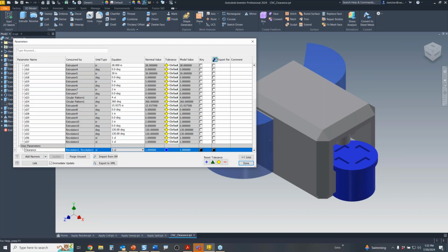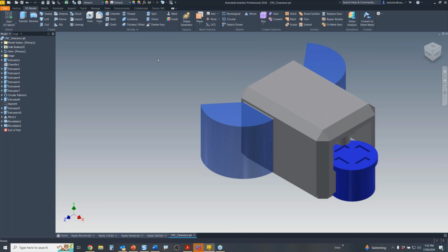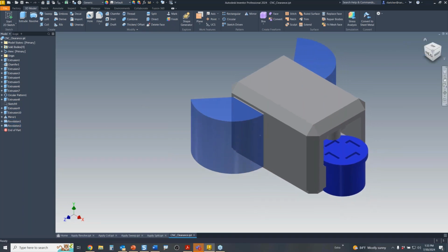And now I could do all kinds of things with this, because some of our parts have clearance zones. Sometimes you want to show them, sometimes you don't. So you can build in that. This is something you might do with a model state in the newer versions of Inventor. But before we had model states, we had these features, and it helps to remember these features. If I've got time, I'm going to talk about some iLogic, and the neat thing about iLogic is I don't need code most of the time if I can remember what was originally built into the application.